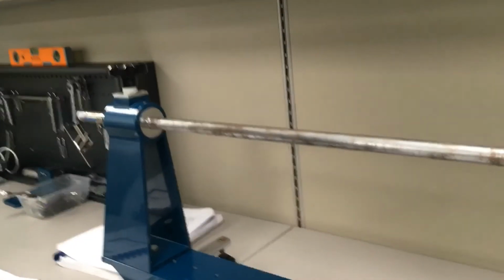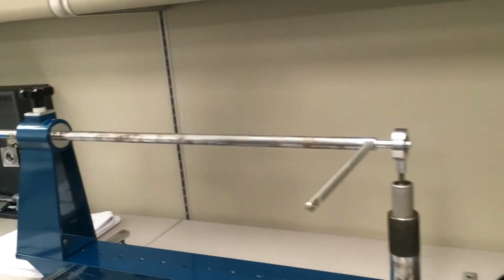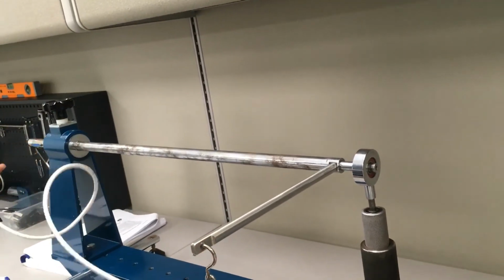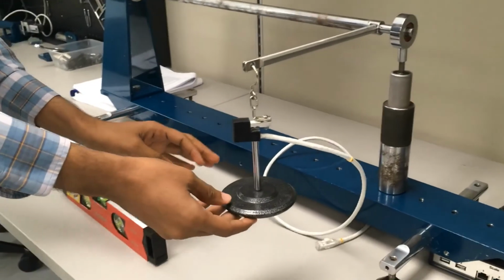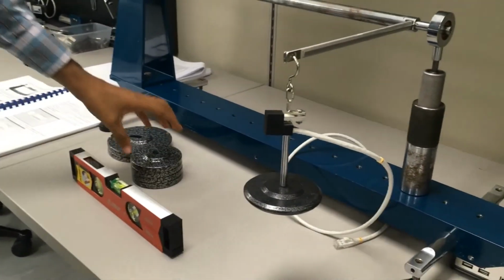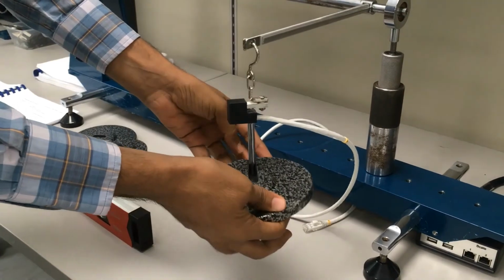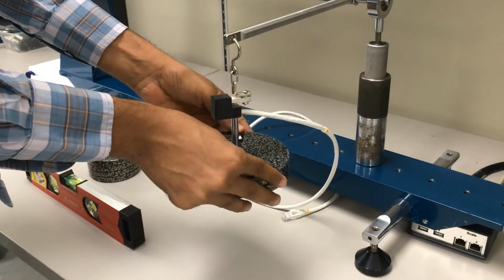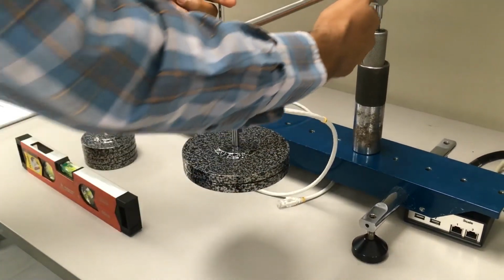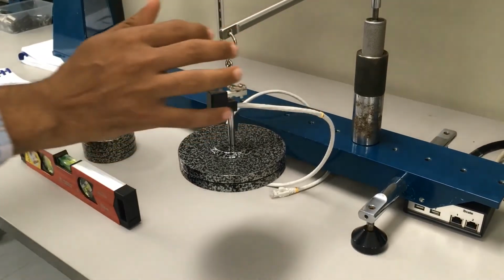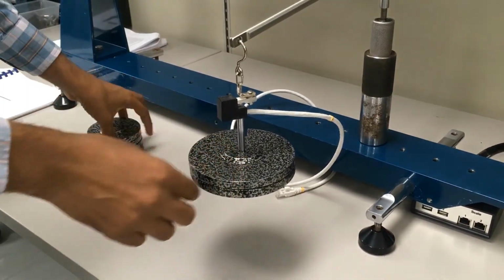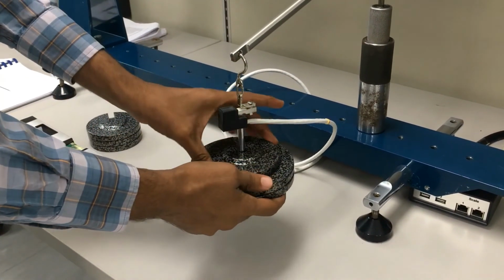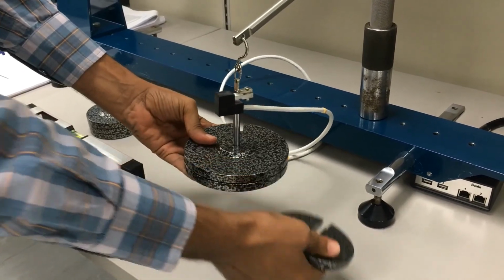Good. And last step, I need to attach this item for hanging loads. So this will be our measurement tool to apply the external load. Example, this is 1 kg. I will put this one in here. Because of this load, because of gravity and weight effect, I will have some deflection. This will be the arm, and I will have some moment for the shaft. Each time in the experiment I will apply one more load, and then I will see what is the deformation because of that load.